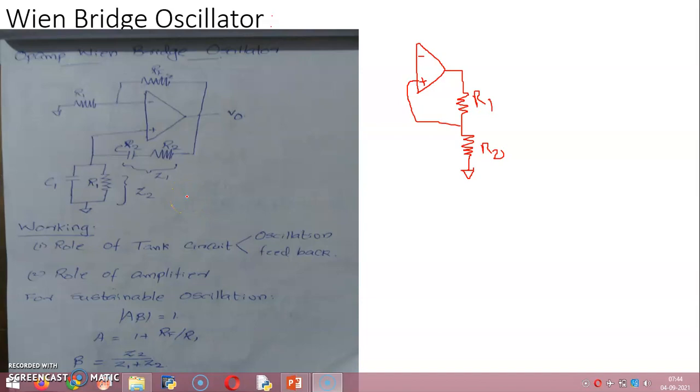As you might be aware, positive feedback will often be employed in the case of oscillators or signal generators that will convert the DC energy into varying energy or AC energy, so that the output of an oscillator can be a square wave, a sawtooth wave, a triangular wave, or a sinusoidal oscillation. We will now see a very classical oscillator, that is the Wien bridge oscillator, being constructed using an Opamp.